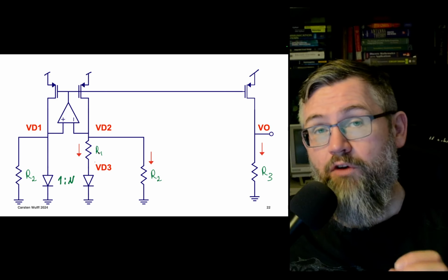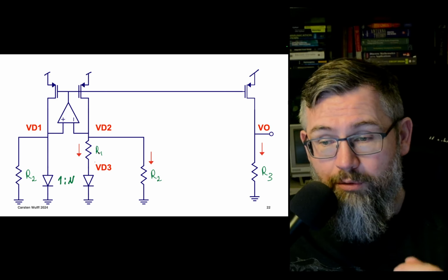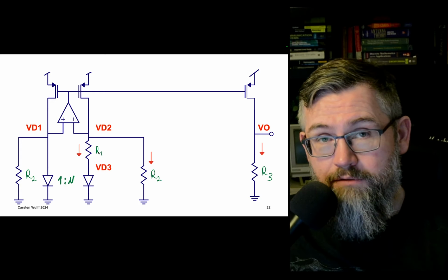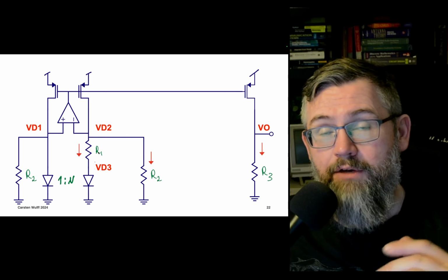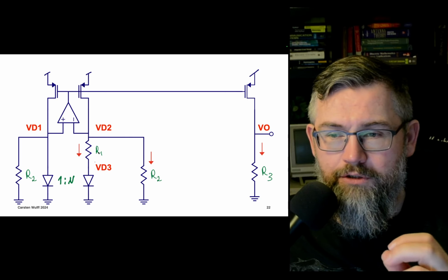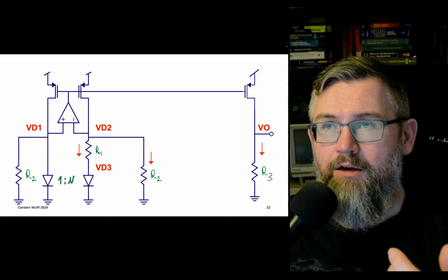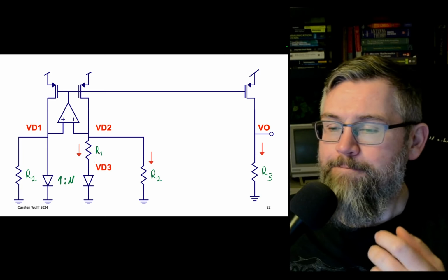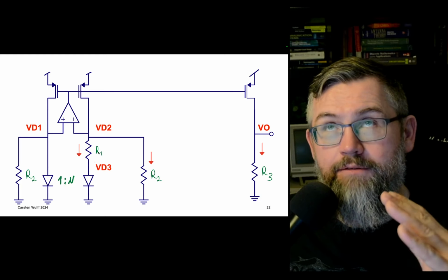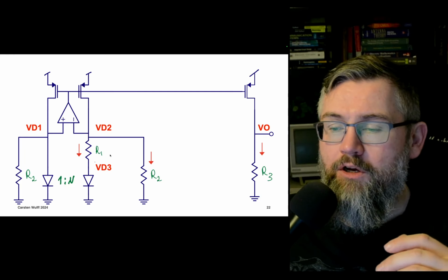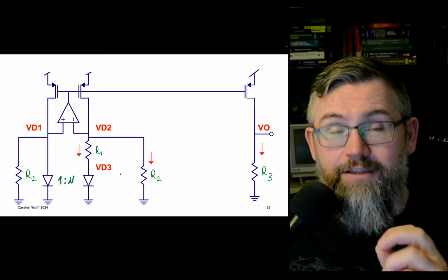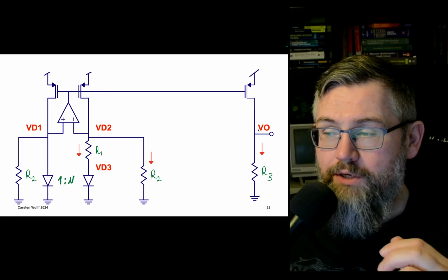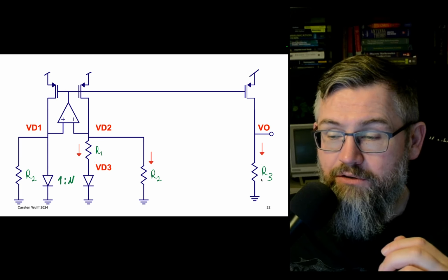Depending on the type of doping on the polysilicon and the type of material, it can either have a positive or a negative temperature coefficient, but it does have a temperature coefficient. So for example, if you choose a P plus poly, then usually that has a positive temperature coefficient. But for this circuit, it doesn't matter that much, because it turns out that the output voltage, although it's a current into a resistor,